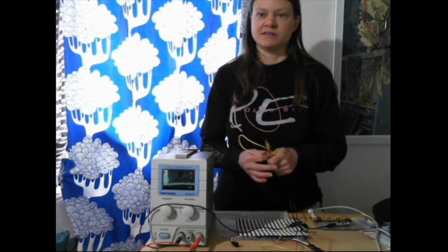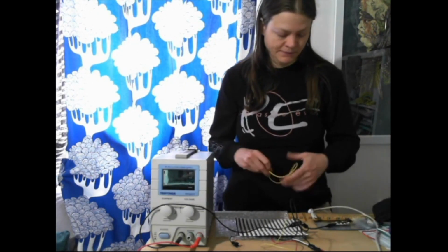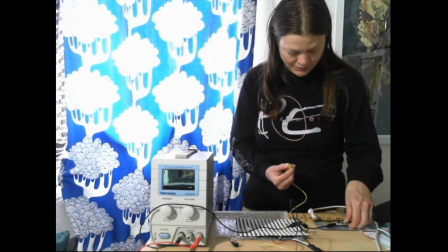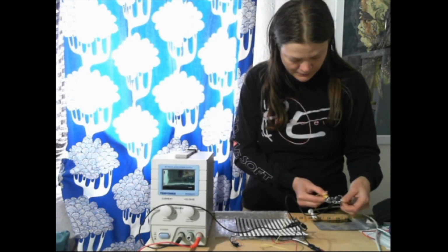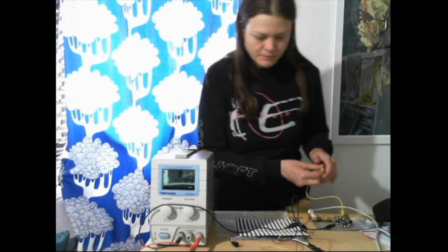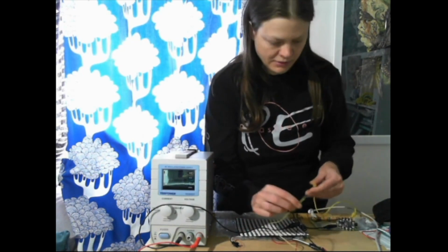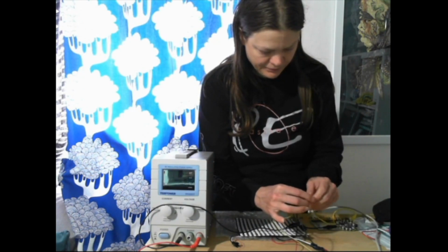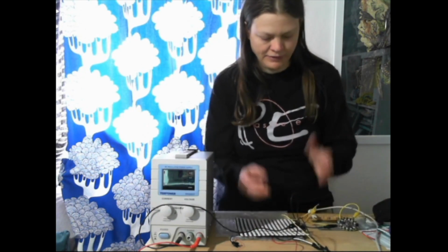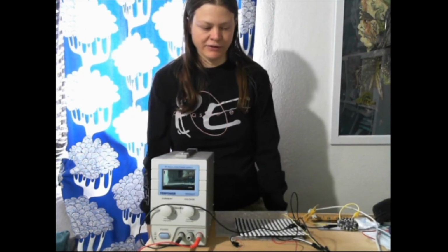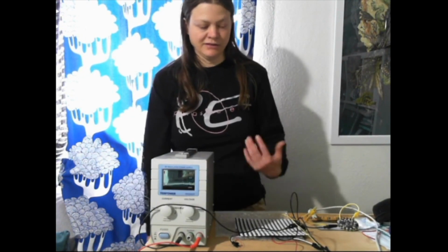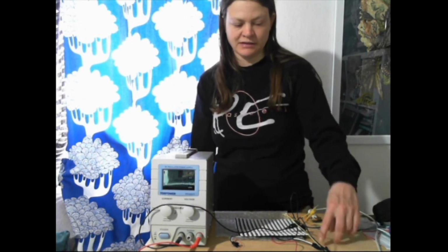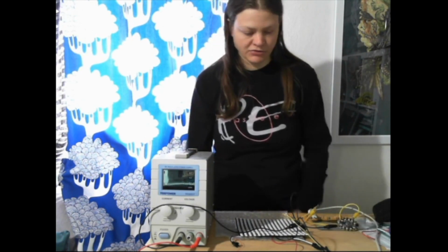And then the next step is get a yellow or blue or green alligator clip. We're going to connect the data line, connect pin A1 on the circuit playground. And I've got my little resistor here, so just connect it like so. And if you have trouble with the resistor, it is perfectly fine to skip it. It's best practice, but these will work without it. So you've got that. You're going to connect that to the data in on this left side of the matrix.